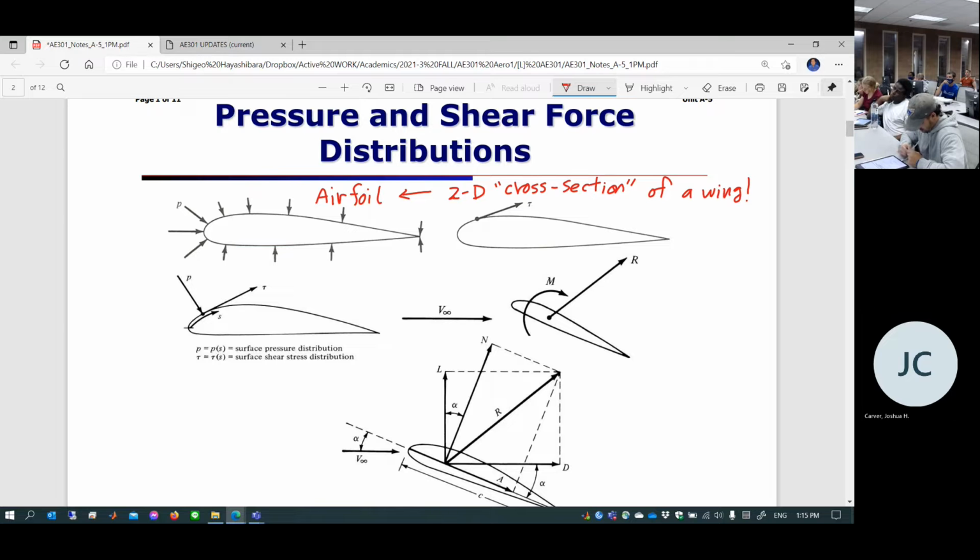Now, in aerodynamics, especially if we introduce the concept of inviscid, have you ever heard of inviscid? What is it? There's no boundary layer. For a moment, let's just ignore the presence of viscosity, because viscosity is the one creating shear stress. Do you know the equation for that, from fluid mechanics? Tau equal to mu, what? Mu dU dy. In other words, yeah.